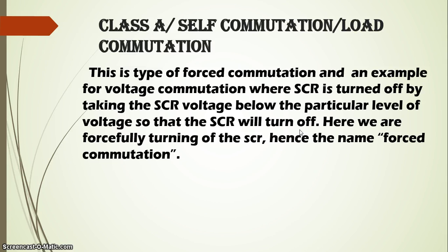This is a type of forced commutation and an example of voltage commutation, where the SCR is turned off by taking the SCR voltage below a particular level so that the SCR will turn off. Here we are forcefully turning off the SCR, hence the name forced commutation.